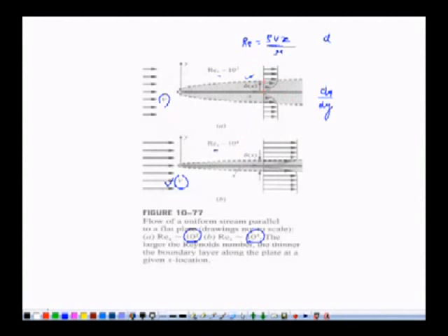It means there is more space to achieve velocity, so the gradient will be less, and here we have a very small distance to achieve the same or high velocity, so du over dy will be very large. When du over dy is large in the second figure, then naturally it is multiplied by mu, and the force will also be very large, right.